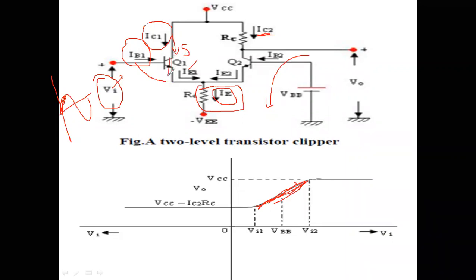This transistor being a closed switch means we are not offering any resistance. In the active region we may have some resistance. Since it is in saturation, from VCC we see two paths, IC1 and IC2. In the IC1 path, the transistor is in saturation mode, so it offers low resistance, and the maximum current will flow in this direction only.